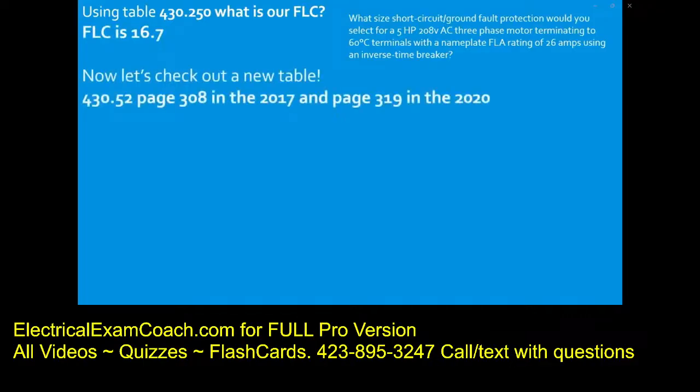So everyone head to 430.52, page 308 in the 2017, and page 319 in the 2020. When we get there, the first thing that we do is we read our black bold heading. It says maximum rating or setting for motor branch circuit short circuit ground fault protective devices. I feel like we're in the right place.